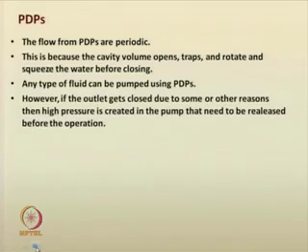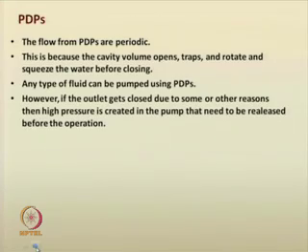You can use the positive displacement pump for pumping those materials. But you need to take care, you cannot operate the positive displacement pump in every condition. If the outlet of the pump gets closed for some reason, a huge pressure starts building up inside the machine, and this pressure can burst the entire machine, so you cannot operate it directly then.